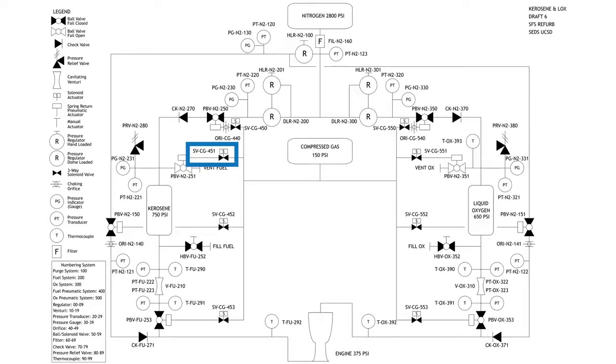That will go into the pneumatic actuator that is the pneumatic ball valve. A 3-way solenoid has 3 ports: one in, one out, but one vent. When you turn off the solenoid, instead of letting that gas sit inside the line pressurized, it'll vent that line for you. So it prevents any residual pressure inside that line. It allows us to turn off the pneumatic ball valve. That's why you need a 3-way.